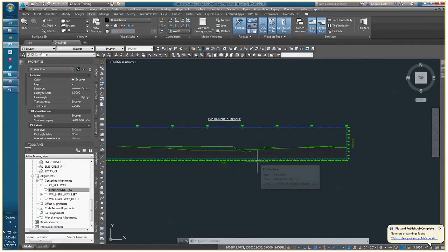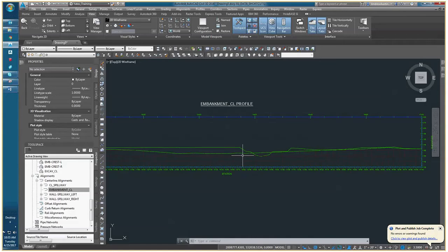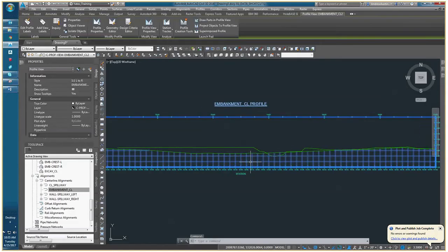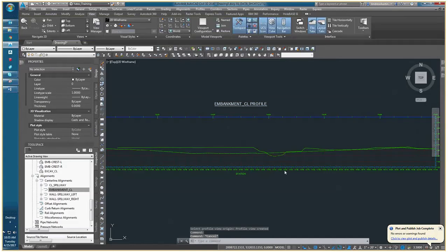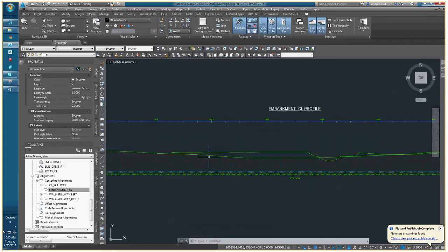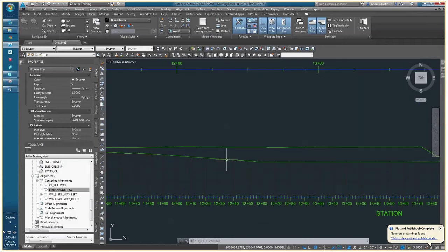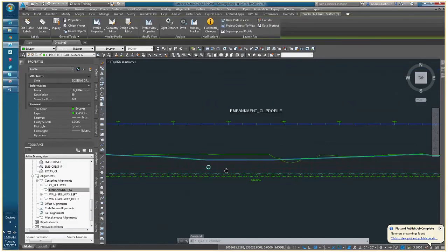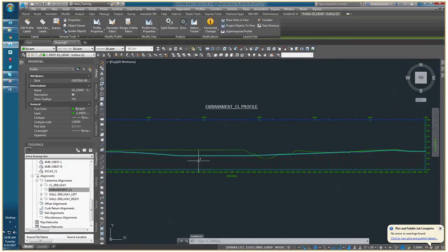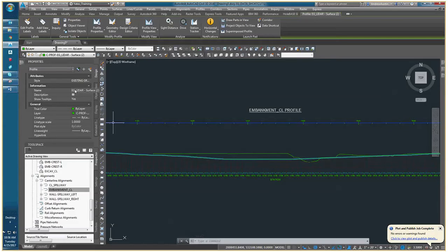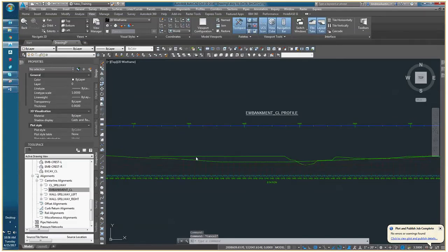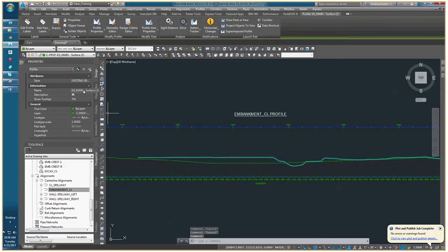Now, what we see going on here is we have our two different surfaces and we have a grid that is being trimmed at one of those two surfaces. Typically what happens is Civil 3D is going to choose to trim that grid based on our template, based on either the lower surface or the first surface that you add to the profile view. And you can investigate which surface is what by clicking on the profile line and then checking your properties menu to see that that's the EG LiDAR. And of course, the only other surface that's in our drawing is the surveyed EG main.